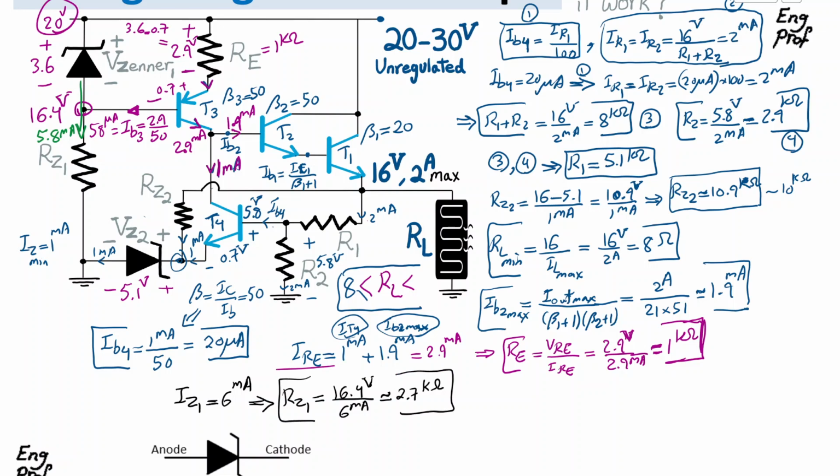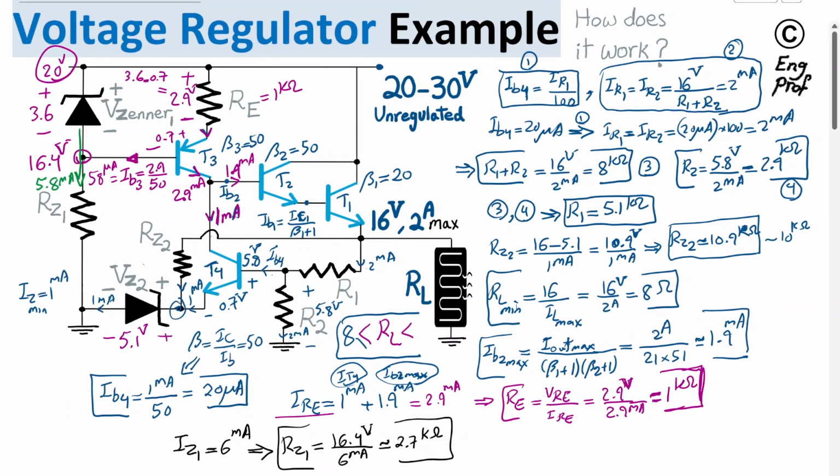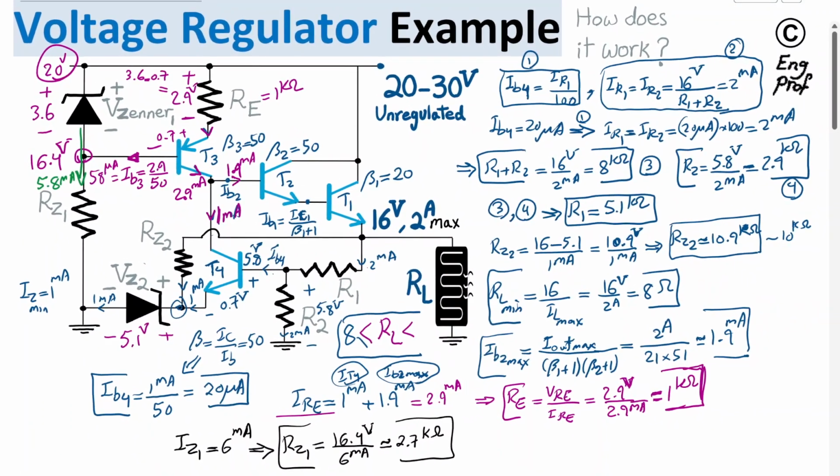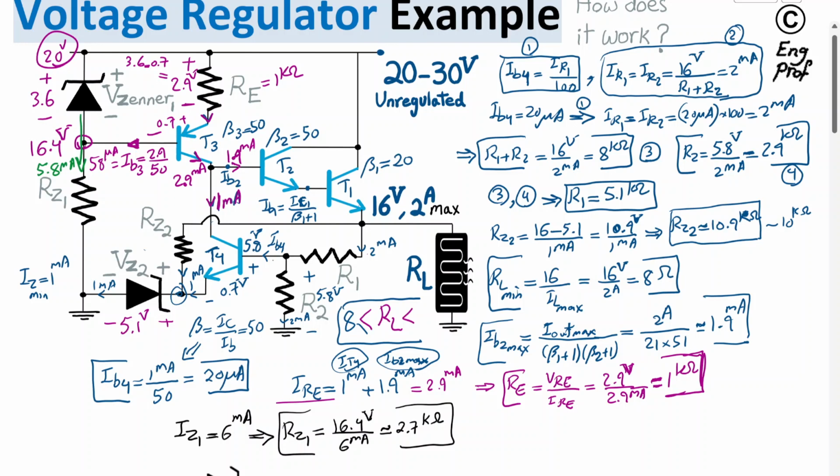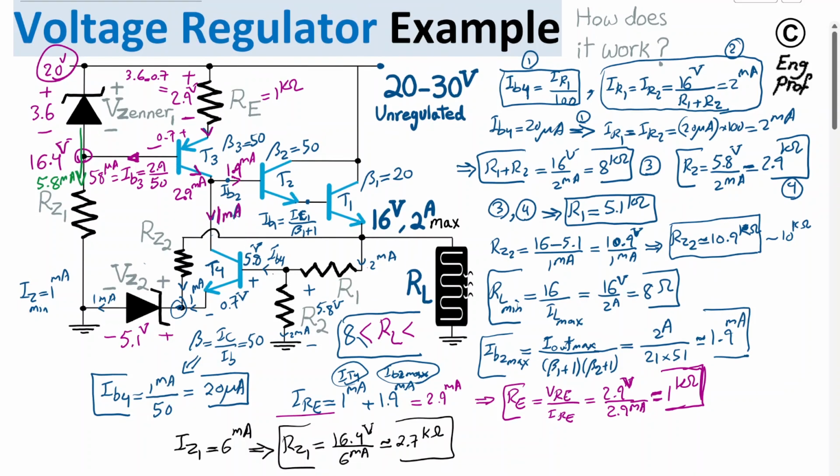This finalized the discussion about the choice of parameters and their values for this simple, of course imperfect, voltage regulator example design. The actual practical design requires more components in terms of protecting the supply voltage and protecting the output transistor not to burn when RL goes below the acceptable value, for example if the output is shorted.